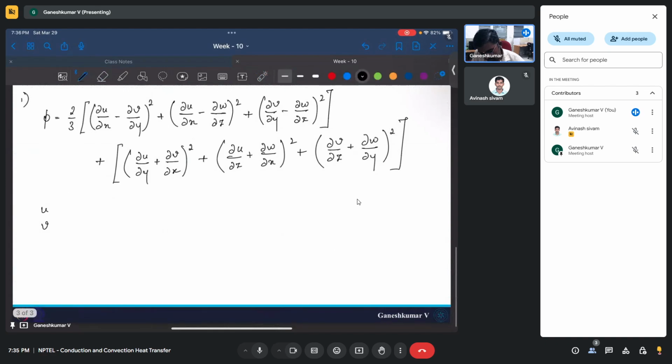So the v component of the velocity is 0, so you do not have any of those terms. The w is, again, this is a 2D, so we do not have that too, so we can just remove those. So v's, w's and all will be 0. You will have only dou u by dou x or dou u by dou y. These are the two terms you will have.